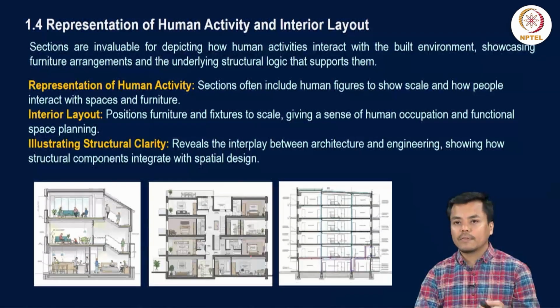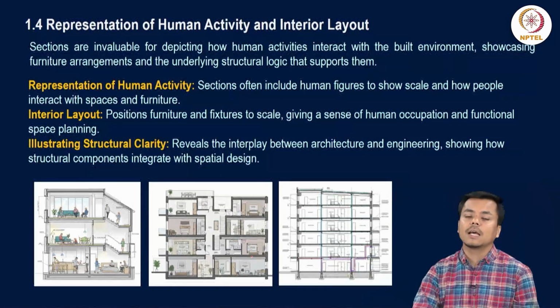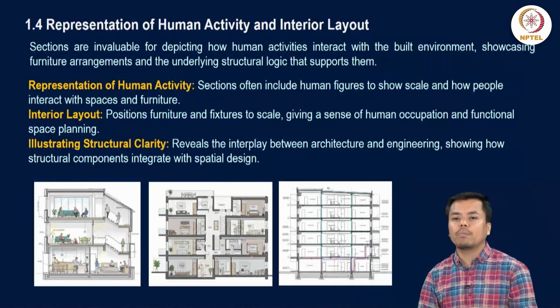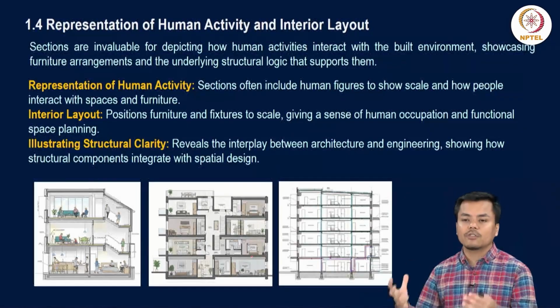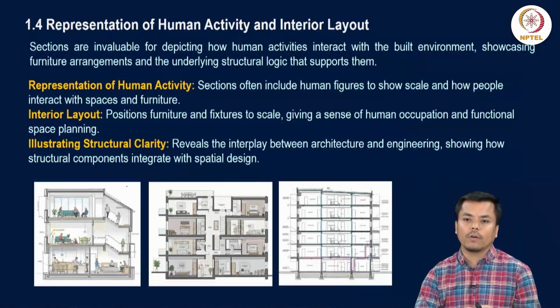Then the representation of human activity and interior layout in your section drawing. Sections are very important to showcase the human activity. Though you showcase that in your floor plan, to visualize how that space will actually be used, that can be understood from the sectional drawing. One will understand how the staircases are going to be used, how the internal spaces are going to be used, by placing human figures and showcasing the activities to be performed in all these spaces.